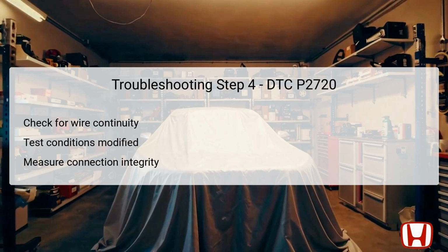You will measure for continuity between the designated test points, ensuring that the circuit connecting the solenoid and PCM is intact. You will need to check from the solenoid wire harness, wire number 8, to PCM connector B, wire number 4, under the condition that the ignition is off. If continuity is confirmed, this indicates the LCC-LS wire is operating correctly. If not, you will need to repair any identified openings in the wire to restore proper function.